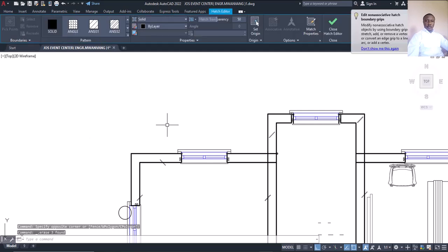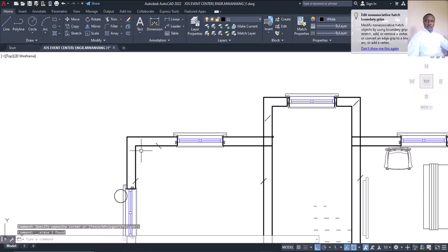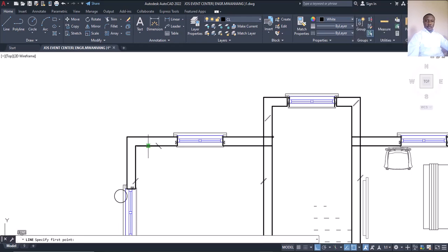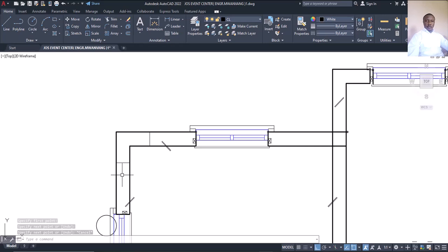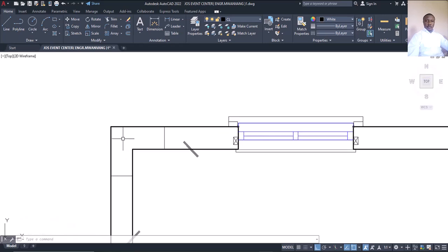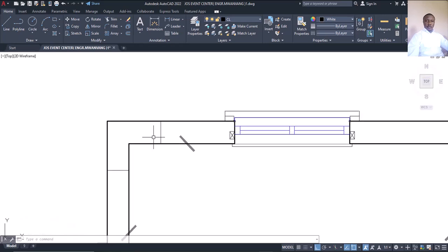I can now go ahead and put, I need to know the center of this line. Is that okay? Center of this wall, rather. The center of this wall. I'll press L, then enter. Is that okay? From this point here, I'll click here. Correct. And also spacebar again to continue. Click here. The essence of this line, it will help me to know the center of this wall and also the center of this wall. Is that okay? Which now gives me the point of intersection at this point. So now I'll pick my construction line.